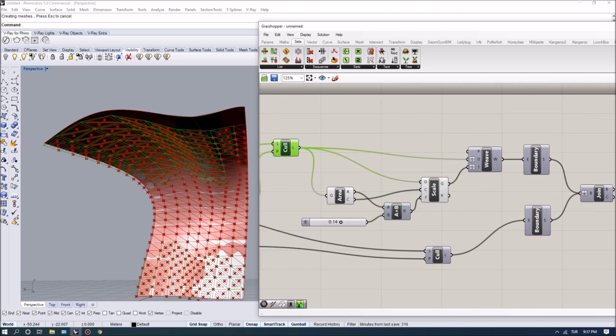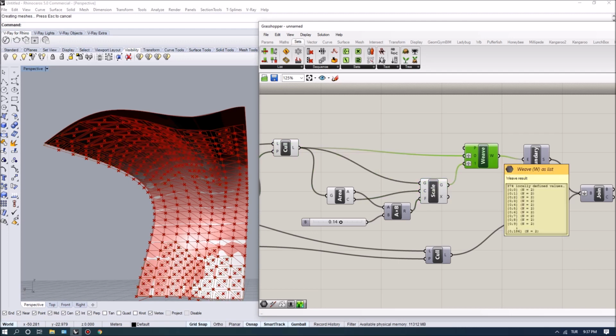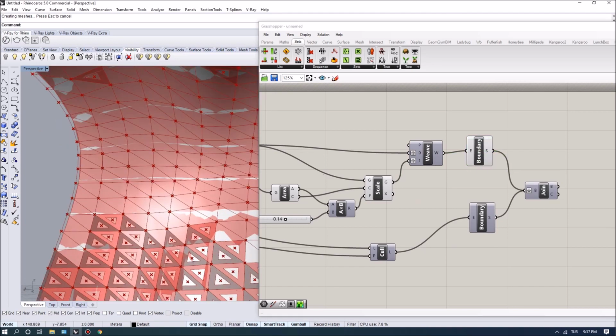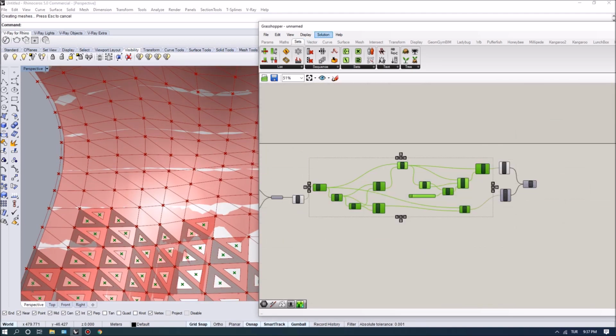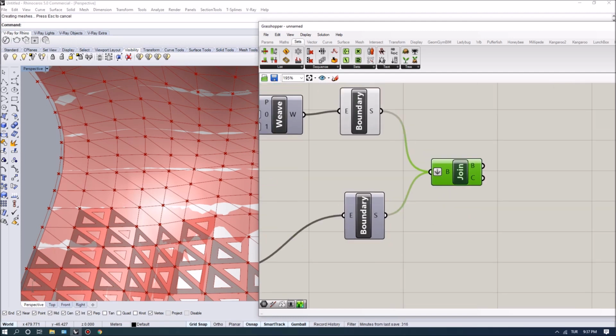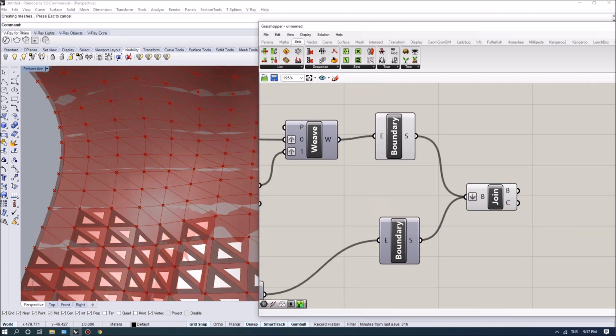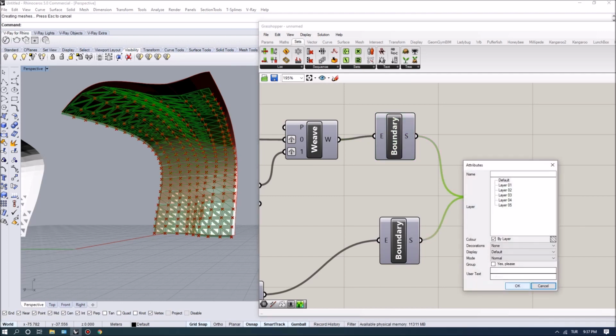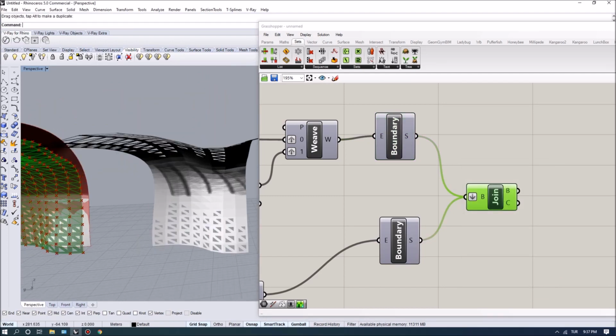And then in the last step, I associated the bounding polylines with the scaled polylines using Weave, and this gives you groups of two that you can define as bounded surfaces with holes in them. And in the final step, I did a Boolean join, so that the result we can simply bake, and all of these pieces will be connected.